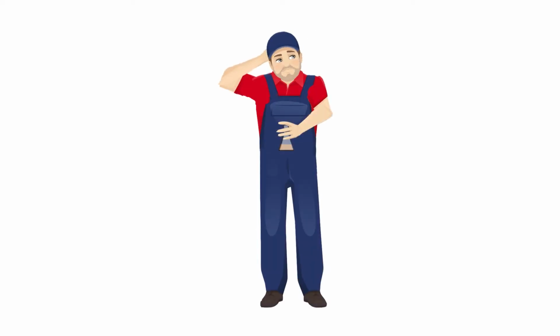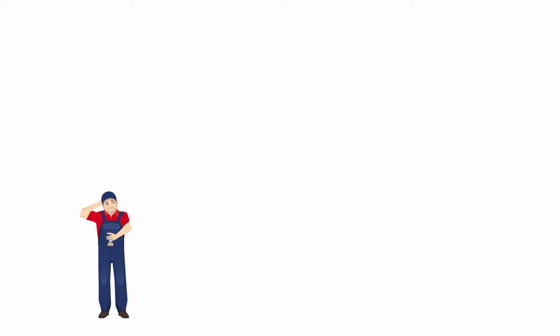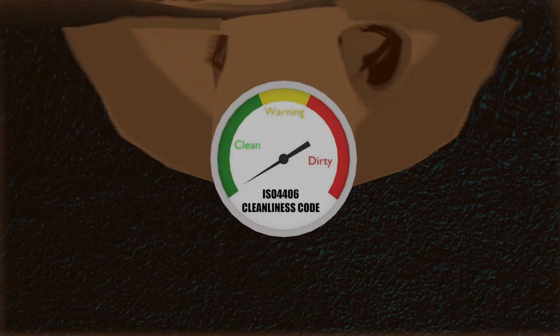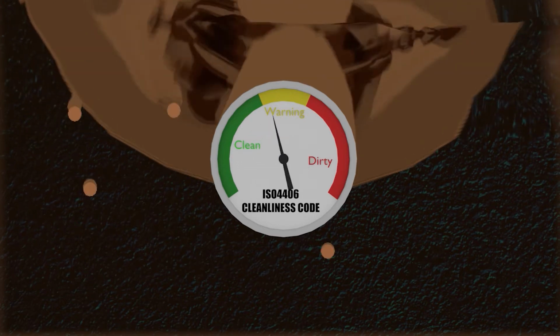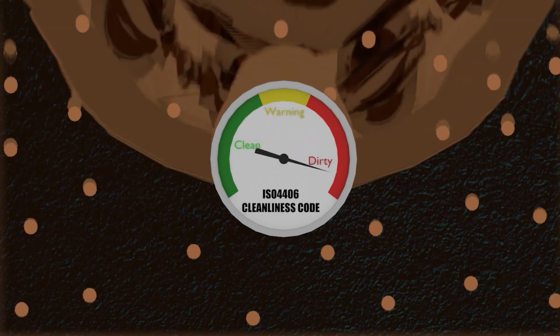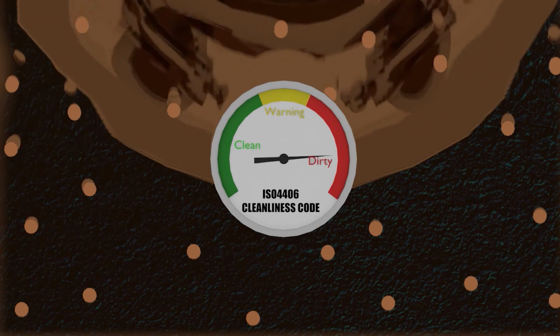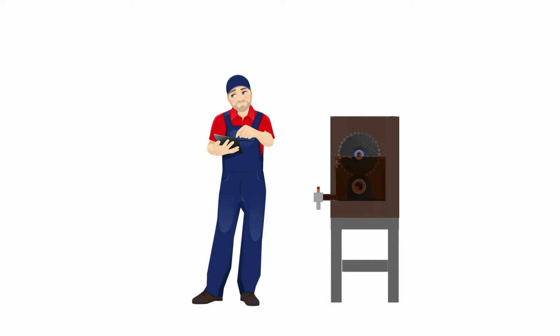What John knew he needed was some type of early warning system for the cleanliness of his oil, similar to a pressure gauge on a pressure vessel, informing him in advance of an out-of-spec operating condition. However, instead of indicating pressure, this early warning system would tell John that his oil cleanliness had exceeded the required gearbox manufacturer's specification, thus allowing John to rectify the situation before his gearbox components failed prematurely.